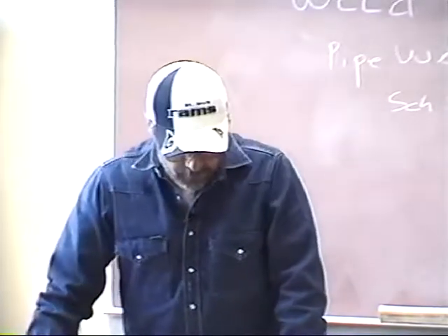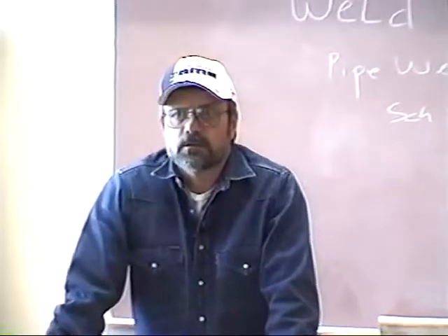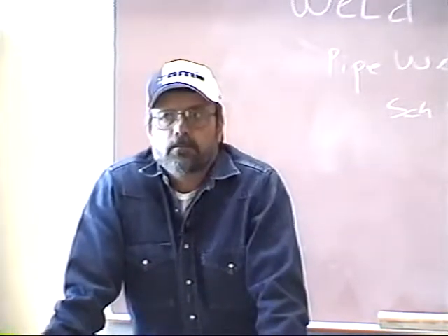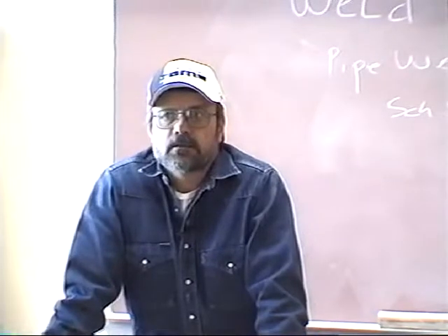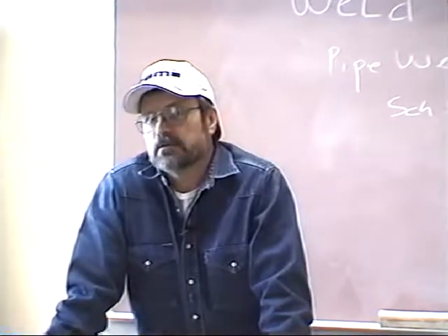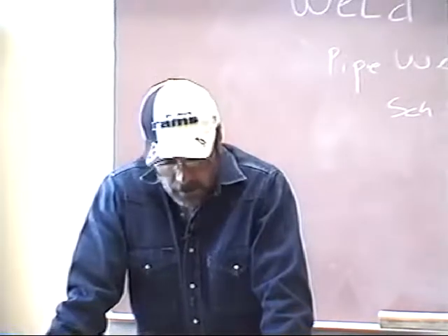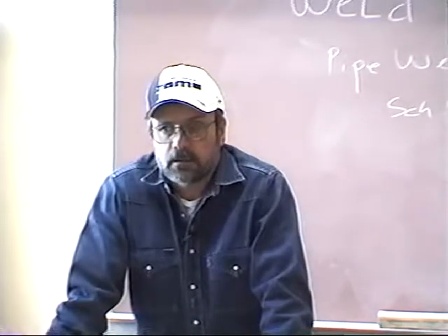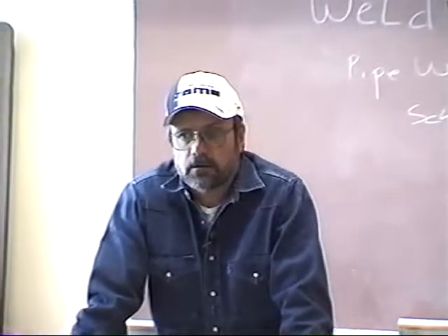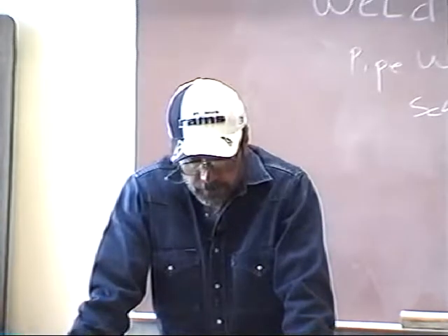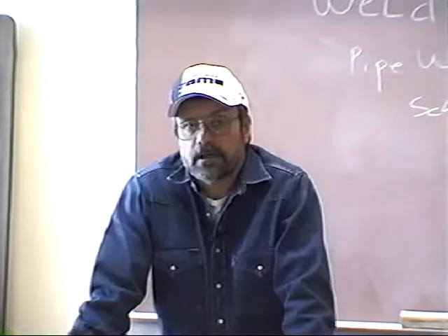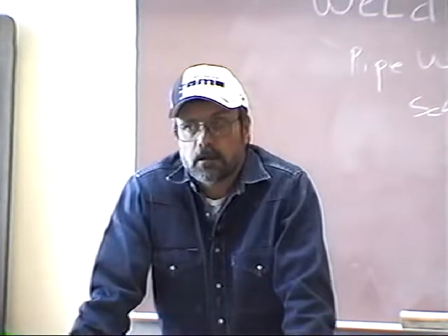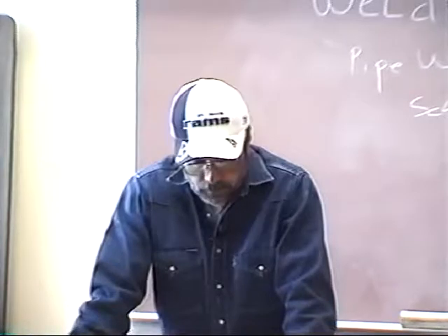Based on that first statement right there, Western is an AWS accredited testing facility, but as part of that facility, we had to have the machines that we use in AWS testing calibrated to national standards. They came in and hooked our machines up to a bank that they were able to use to calculate the heat output of each of our machines to within 2%, and that's enough to qualify for AWS standards. Most of the machines, fortunately, that we have in the welding lab are very accurate, very close to what they read, especially those with digital readouts.